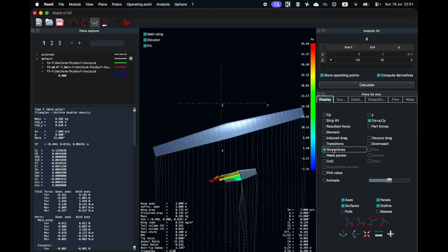Therefore, the lift produced by the vertical stabilizer points to the left. Since the z-axis is pointing upwards, this produces a negative yawing moment around it by right-hand rule.